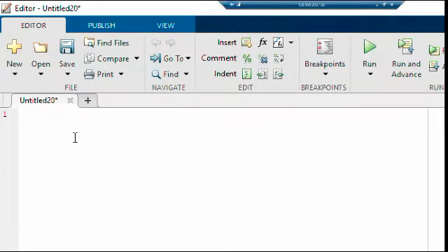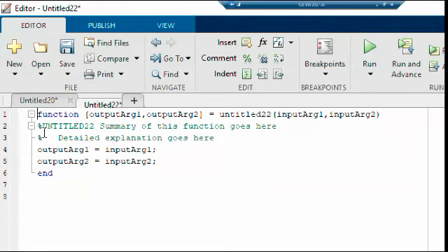So in this part, guys, I'm going to teach you how to make your own matching network using Matlab, and how to make it customized, so that you can find your own matching network. Since I'm going to use optimization, I'm going to first define my cost function, which is something like my goal function. I first make a new function, and I'm going to call it my cost function.